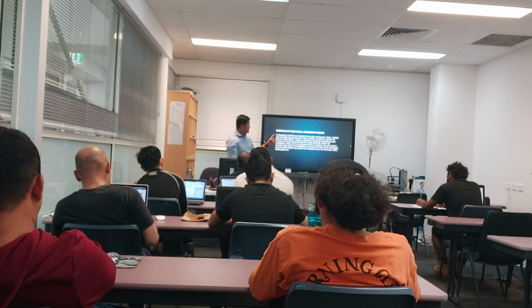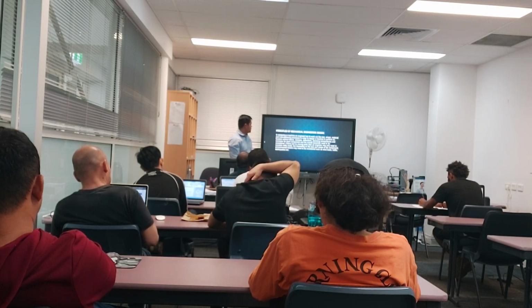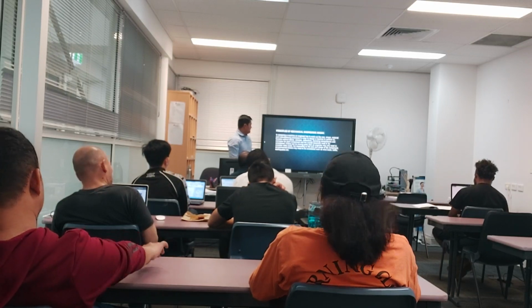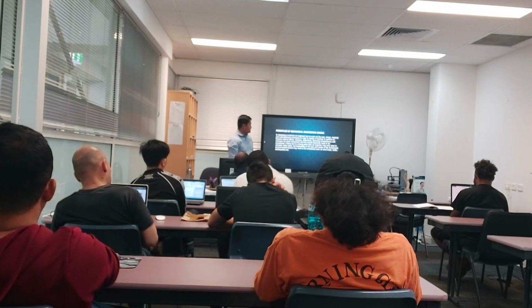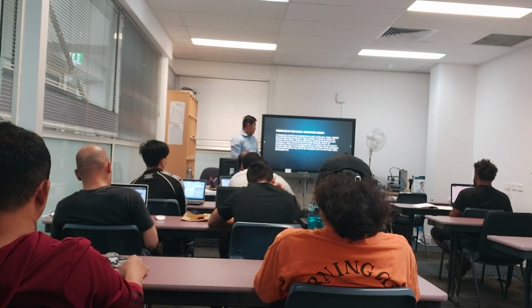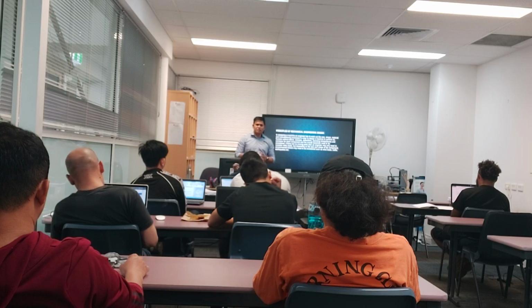So stresses, deflections, operating temperatures, and corrosion for each component and the overall assembly need to be considered. If there are no moving parts, then an engineer may only need to consider static loads, but depending on the size and shape of the component, environmental factors may need to be considered, such as wind loads, traffic, and earthquakes, etc.